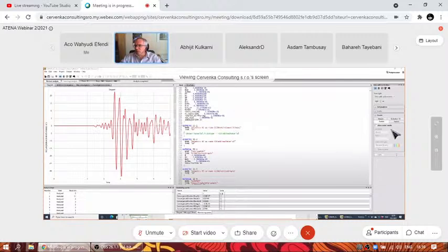That means D plus 0.3 L. Yes, we already answered the question from the applied dead load and live loads in the previous interval. Exactly. In the previous intervals where I was applying the dead load and live load, I would of course apply the live load only up to the level that we need to consider in the seismic analysis.